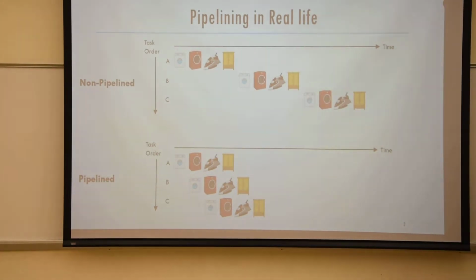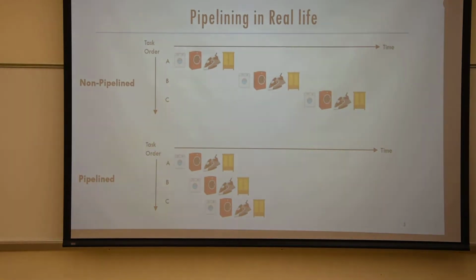In other words, if you're thinking about operations, maybe one register gets populated after an add instruction, and if that register is used in another instruction right after it, I still have to wait till the proper value of the previous add instruction really gets into that register before I can start using it in, say, a jump instruction or something like that.